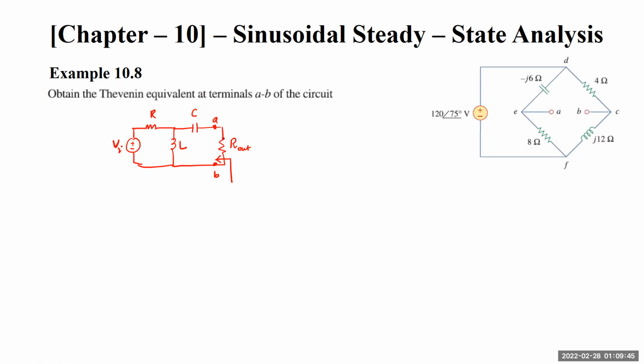And generally when we solve this, we have to make an equivalent circuit that looks something like that. So this is Z Thevenin and something that is RL. And remember, this concept is extensively used when we use the concepts of maximum power transfer out of any circuit.